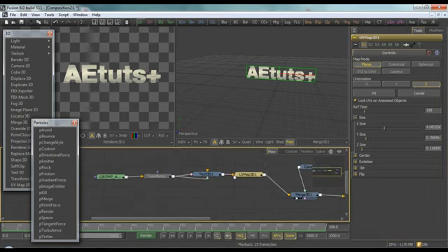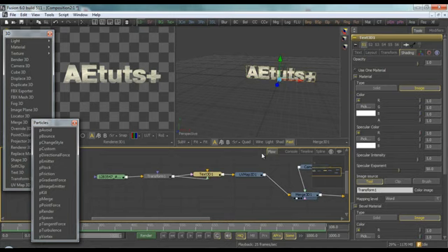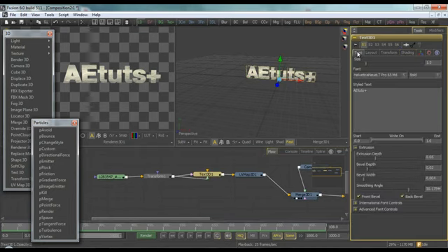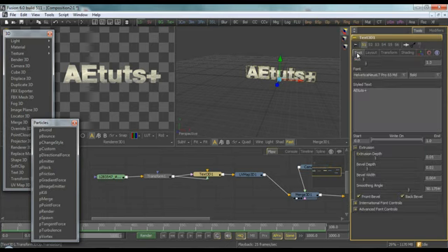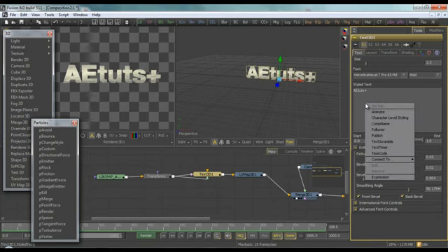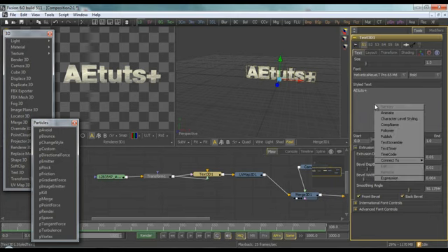One more thing on text. We'll set up the animation, but we won't set it up here with the transform mode, 3D controls as it's called, but we will rather animate it differently. We'll set up the modifier, and you can do it by clicking the right mouse button on the text area and selecting follower.